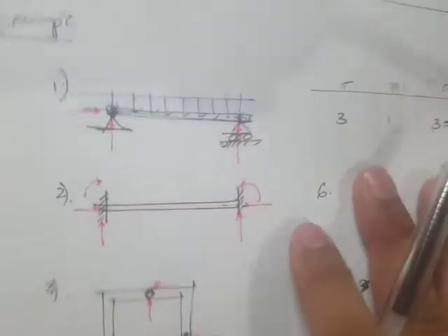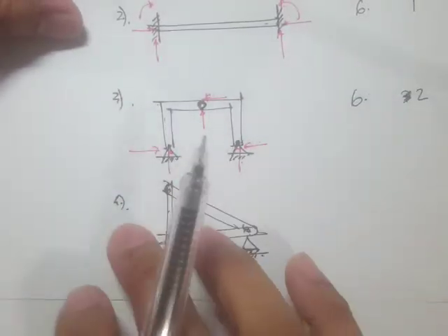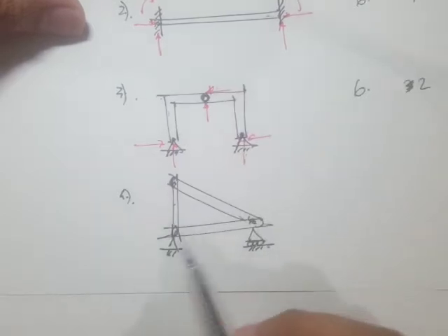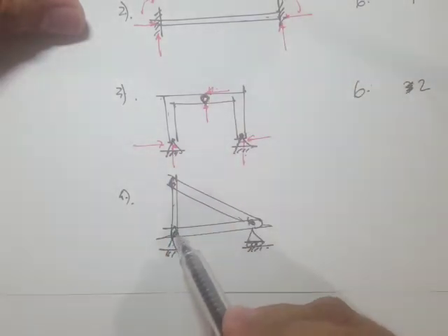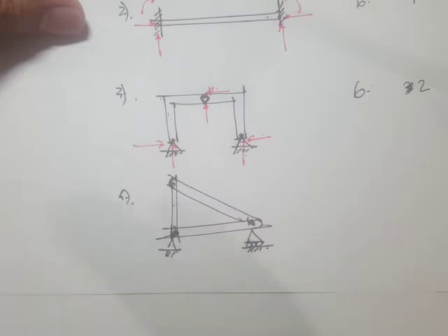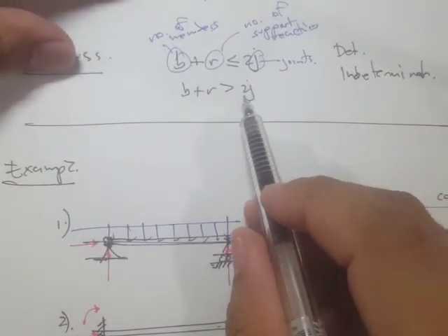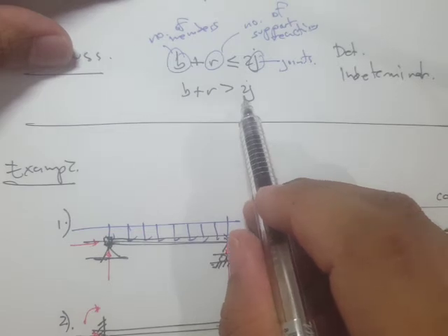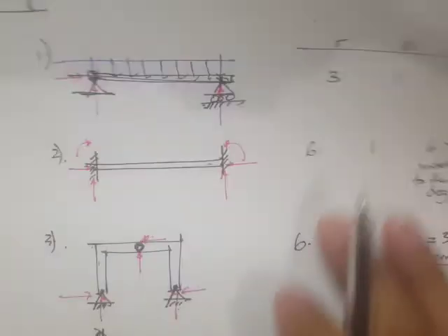Now for a truss, my technique is to think about the equilibrium equations applied in a joint. If I apply the equilibrium equations in this joint, how many equations do we have? We only have two, because we have summation of forces along x and along y, and the summation of moments does not come into play because there's no moment arm.